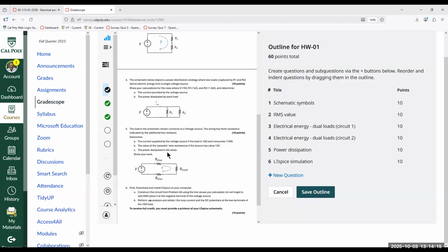So our voltage drops across the resistors. The point of entry of the current is always positive, okay? So for our source, current goes from low to high, minus to plus. For everything else that is receiving energy, current always goes from high to low, meaning from plus to minus. For all the resistors, if the current is flowing from the top to the bottom, then the voltage will have a polarity of plus at the top and minus at the bottom.